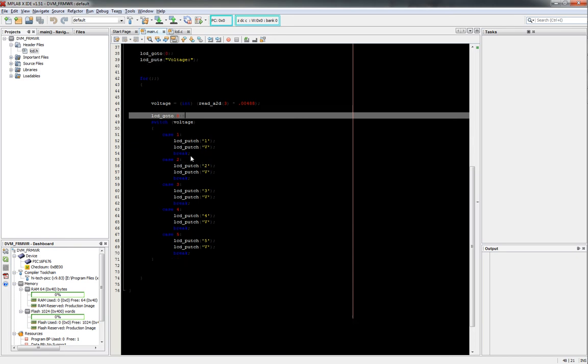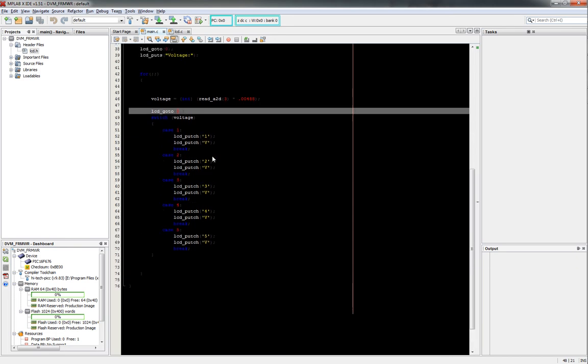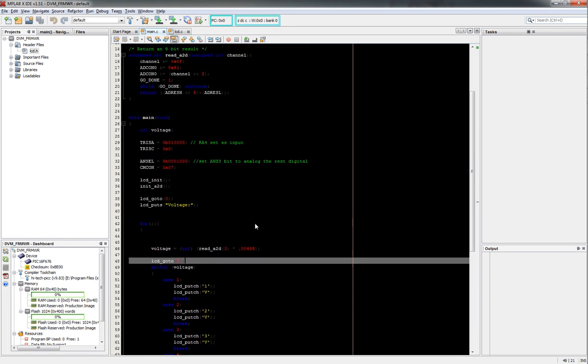Okay? So remember that when you put CH and you're putting characters to that screen, they have to be in ASCII format, because that's how that screen interprets whatever data you send it. So you can't just print an integer to it. It has to be formatted as ASCII. So that's, I think, all the pitfalls that I can think of.